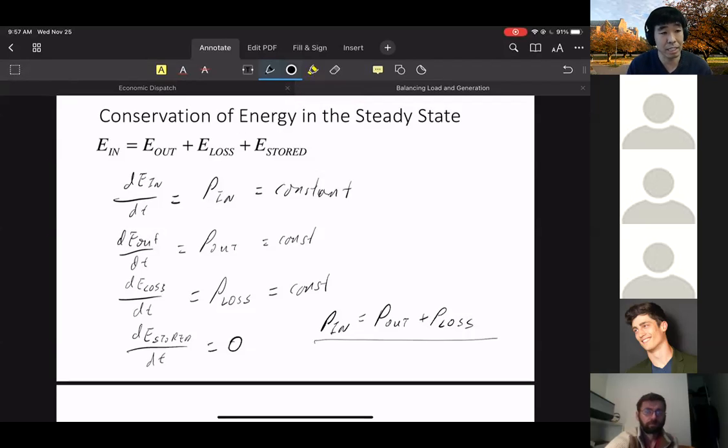Even if the generator changes a little bit, the frequency or the rate of rotation will increase a little bit, will decrease, so we'll always hover around a steady state. Right? So that means at least in the average sense, the net change in energy storage should be zero. Otherwise, the system is not sustainable if it has a non-zero rate of storage. So in an average sense, the storage should work out to be zero.